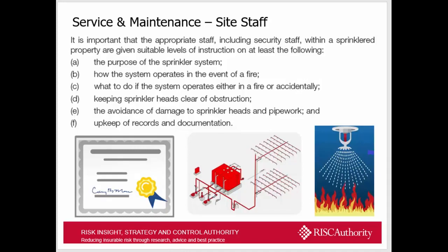Maintaining a clear space around the sprinkler head so that it can operate correctly and control the fire underneath that sprinkler head or within that area. The avoidance of damage to sprinkler heads and pipework, which you get in warehouses where they get hit by forklift trucks, or in plant areas where things get moved about and sprinklers get damaged. And most importantly, the upkeep of records and documentation.